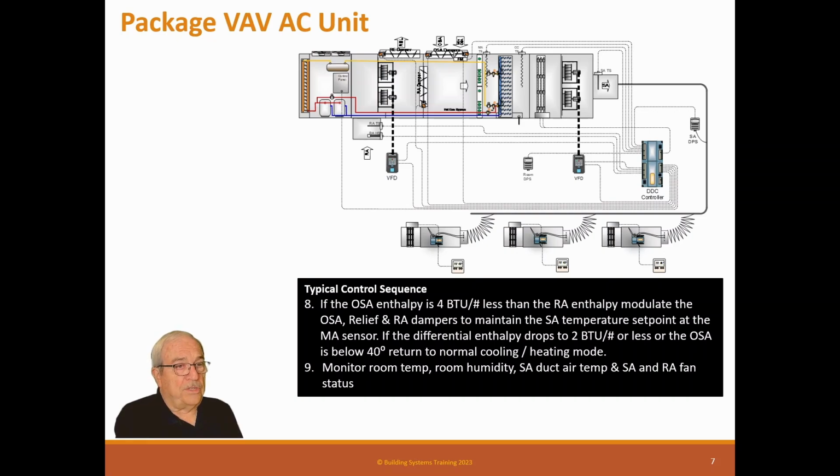This thing is wasting energy, it's just blowing cold air out the economizer, or vice versa, warm air out the economizer, and they just shut it down because it's too complicated to figure out right now. They've got to stop this building from bleeding energy, so they lock them off. When you get there, you'll see they're not working, and then you have to go figure out what's wrong with them. But economizers are problematic to keep working, and to do that, you need to keep the sensors calibrated.